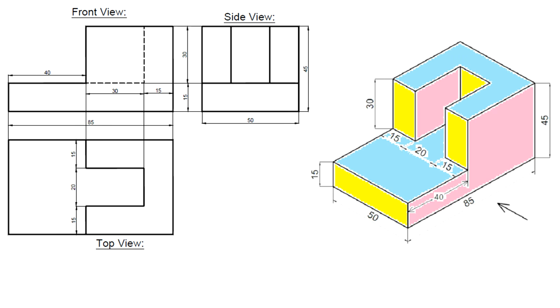If you see the top view, we will get this C shape, and then these another two shapes. So these two are principal surfaces. We will be drawing these principal surfaces with the true dimensions, and then we go to the side view. They have given the left side view, so that will be drawn on the right side. Then, yellow color, four surfaces one after the other will be visible. So that is how we will be drawing the projections.